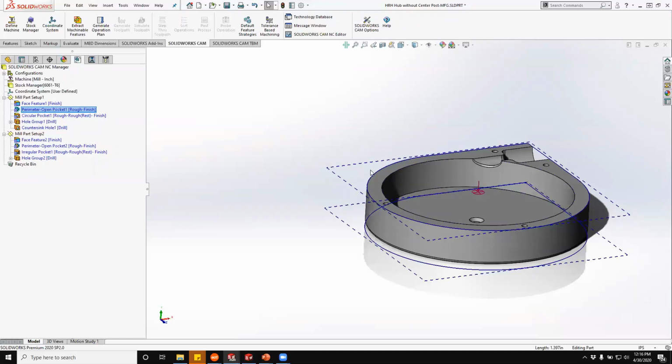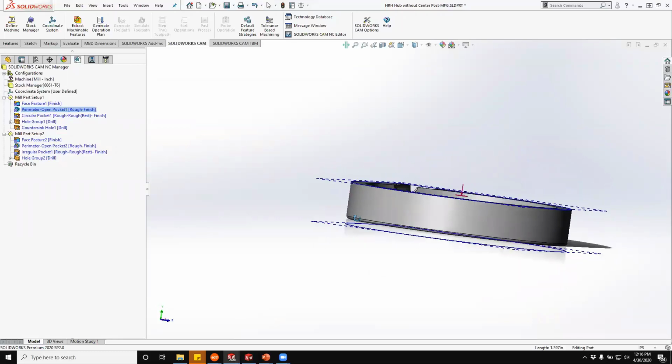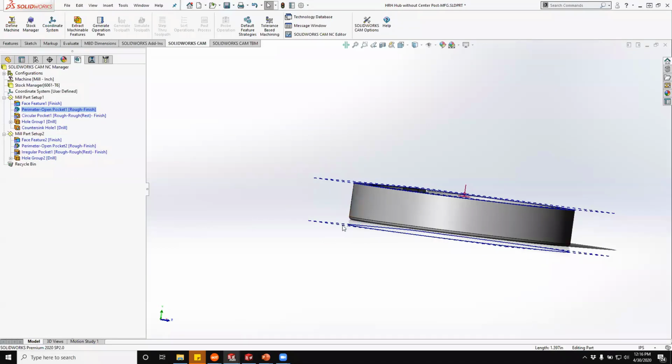On the screen, you can see some solid lines and some dashed lines. The solid lines represent the fixed edges of the part. Those are the things that you better not violate, or else you're going to scrap your part most likely. And then the dashed lines represent the open air edges of the part. That is the places where we actually have to machine beyond them if we're going to make the part correctly. You can see the system knows where the bottom of the stock is, and it's automatically extended that feature down to the bottom of the part.